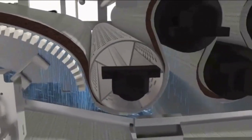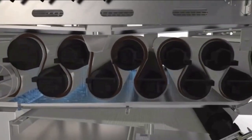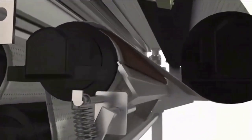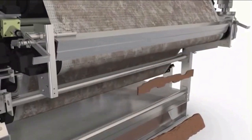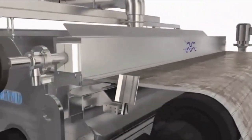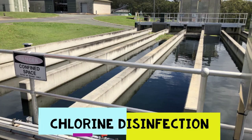The water collected from the drying process is directly sent back to the oxidation ditch for further treatment. And the sludge comes out as sludge cakes, which are dry and ready to be sent to landfills. The belts are then washed off. The plant produces about 15 tons of filter cakes daily.